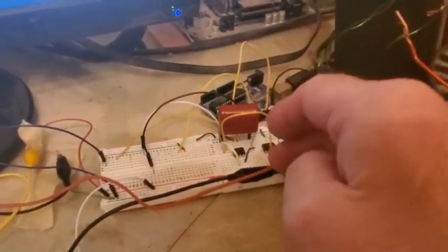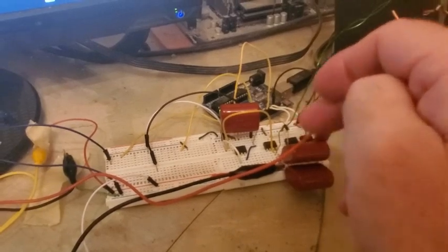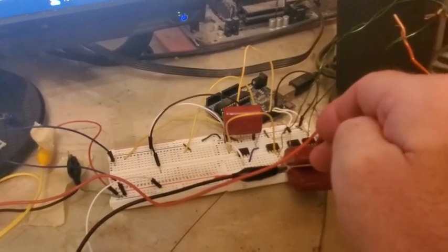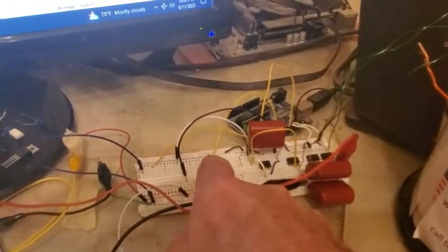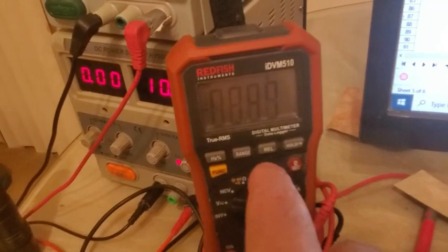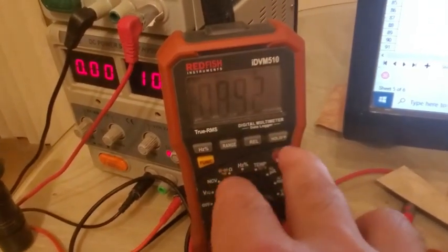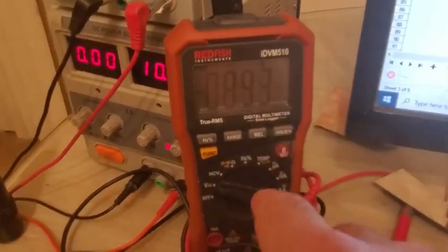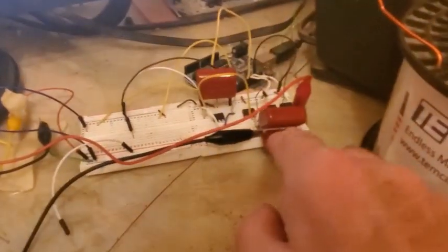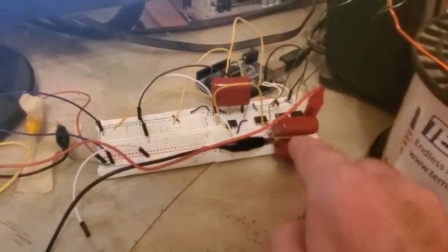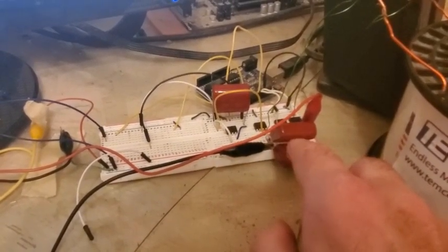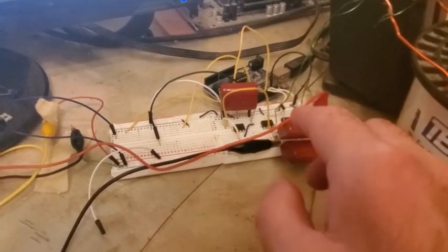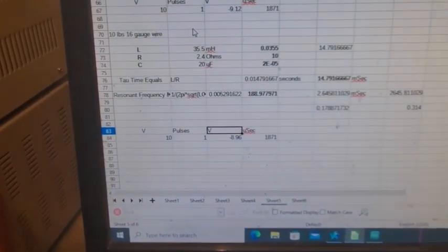But what you could do, and I'll probably do this, is take like a 1 UF cap and say it goes to negative 8, and then just have another switch where you shunt that out to like 100 UF cap. And when you do that, when this thing is like under 1 volts, I think it's a different resistor network, you can get a good solid reading. So then you could extrapolate backwards as to how far negative it swang with the 1 UF, and I think you can get away with a 0.1 UF cap too. So the capacitance makes a big difference.